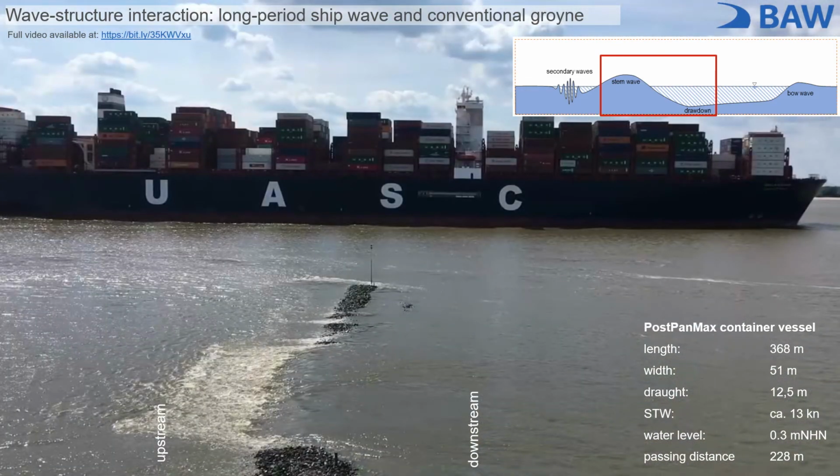Now, this video shows a sort of worst-case scenario. The exact nature of the wave structure interaction, as in whether overflow events occur and how severe they are, is highly dependent on the ambient water level, the structure freeboard, and the exact nature of the ship wave and the ship passage. So they don't always occur, or they can occur and not be so severe, but they can also occur and be very severe.